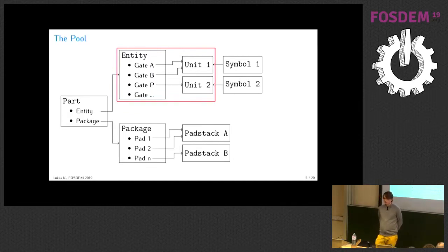And these pins also have alternate names, since these days you often have microcontrollers or FPGAs where a single pin has like 20 functions. Some people then just put only PB0 in there, and you don't know if that's I2C or SPI. In Horizon, each pin has one primary name, which would be PB0 in that case, and you can have as many secondary names as you like. So in the schematic, you'll be able to pick which name will then appear.